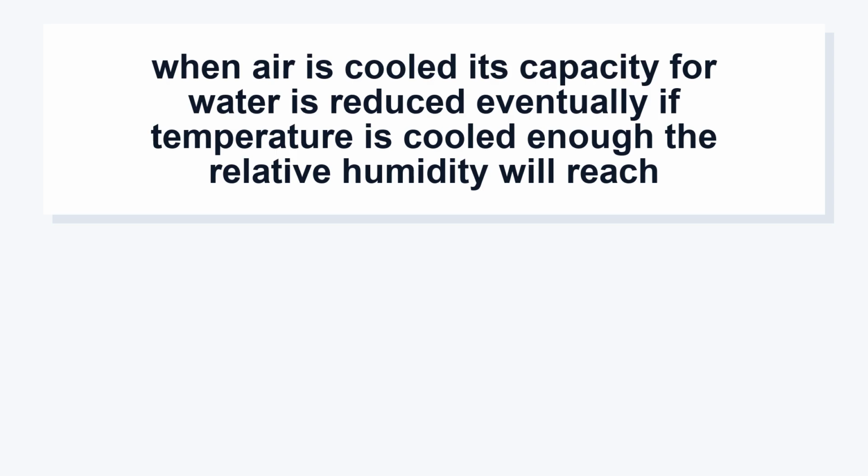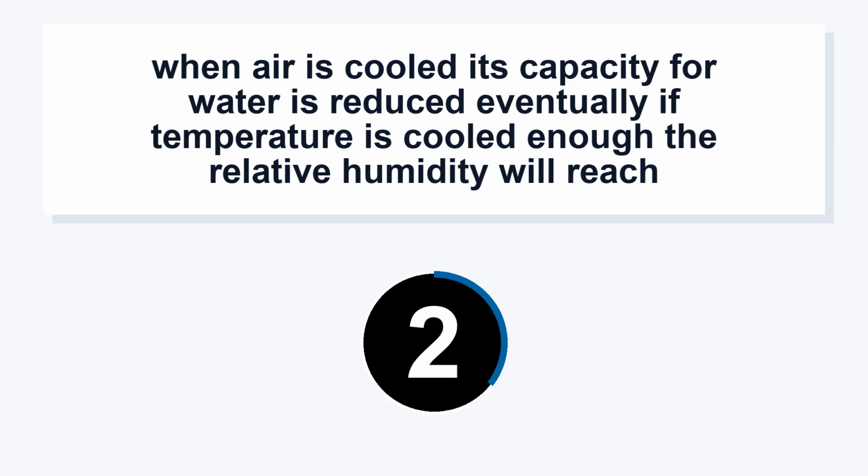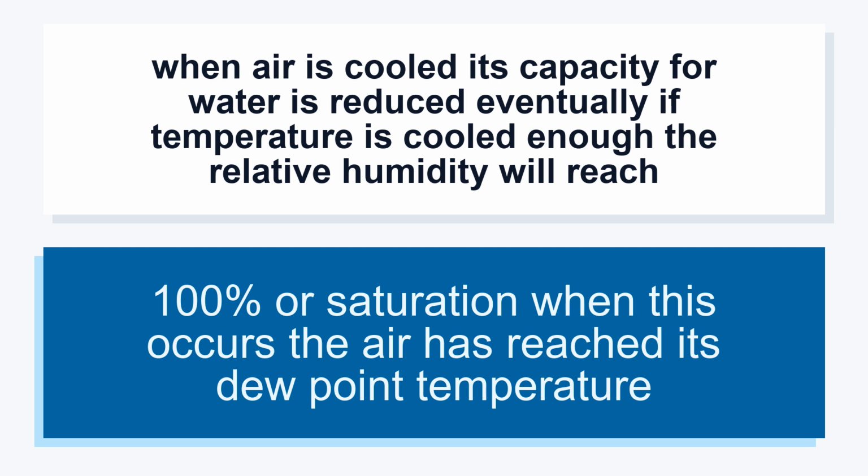When air is cooled, its capacity for water is reduced. Eventually, if temperature is cooled enough, the relative humidity will reach 100% or saturation. When this occurs, the air has reached its dew point temperature.